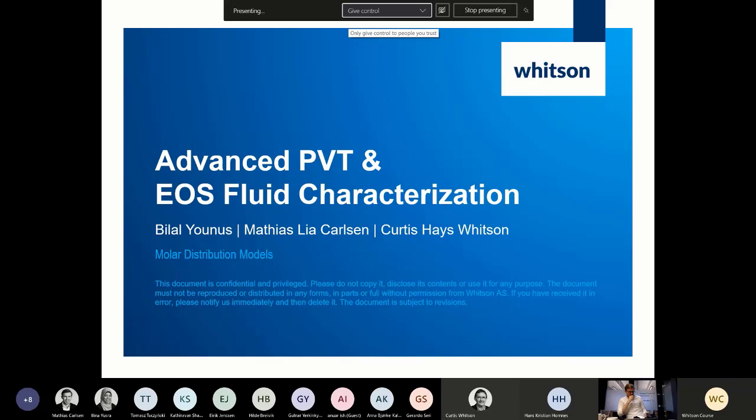In that case, you may have quality issues with the lab PVT data, because there are always some tricks you can do to close the material balances that we had been seeing before. On the material balance, all the data may look very nice, but when you start doing the prediction with that initial EOS model, you may see that some of the PVT samples may not be falling in line with your equation of state model predictions. And there you can start highlighting what the quality issues are, and which PVT data of a particular experiment is questionable from the lab.